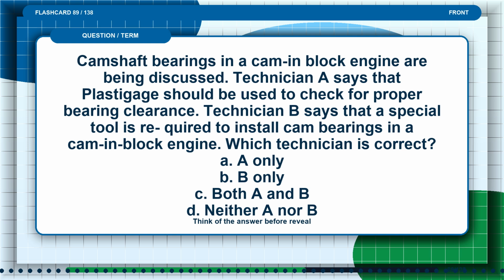Flashcard 89. Camshaft bearings in a cam-in-block engine are being discussed. Technician A says that Plastigage should be used to check for proper bearing clearance. Technician B says that a special tool is required to install cam bearings in a cam-in-block engine. Which technician is correct? A. Only A. B. Only B. C. Both A and B. D. Neither A nor B. Pause and think of the answer before the reveal.